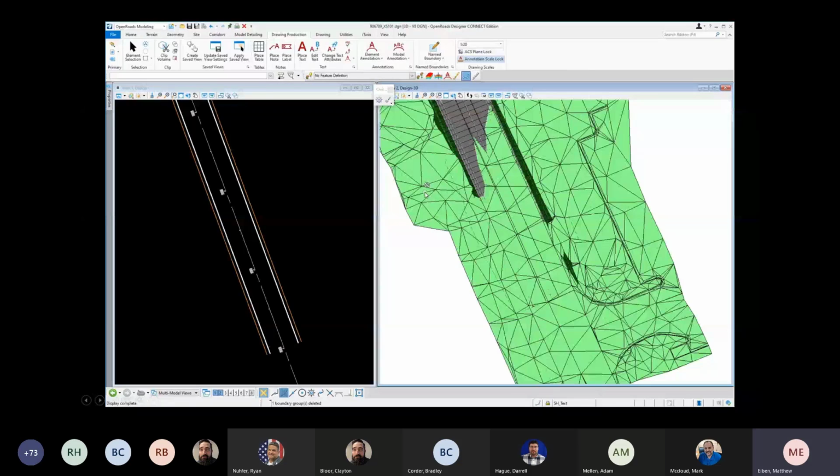All right, so in this demo, I'm going to look at another way to edit your name boundaries, except rather than edit them after they've been placed, I'm going to edit them as I'm placing them. The scenario I'm thinking about is if you need to split your cross section, maybe because your section is too wide to fit on one sheet. You want to show the left side on one sheet and the right on the other. Maybe you're going to use the center line as a match line, or maybe overlap 10 or 15 feet across the center line on each side.